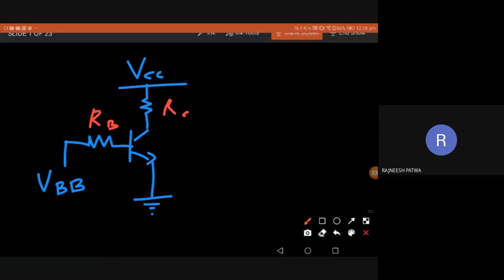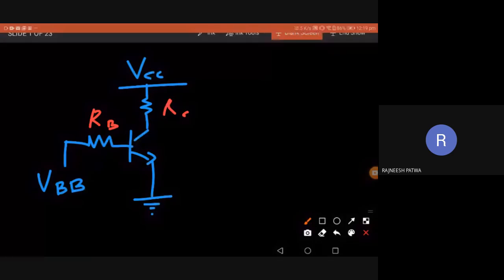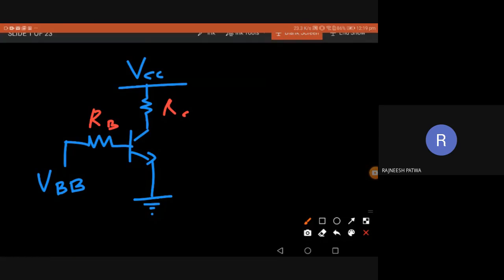Yeah, it can vary. I'm not saying that in a particular circuit we can't take beta as constant. With a fixed circuit, where we design all the resistances, everything, and fixed temperature, pressure, environmental conditions, we can assume beta is constant. But in rare situations, and based on temperature, beta may definitely vary. So to avoid that variation, we design the circuit so that it is independent of beta.